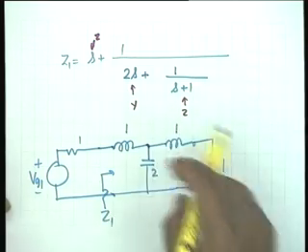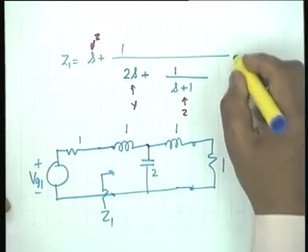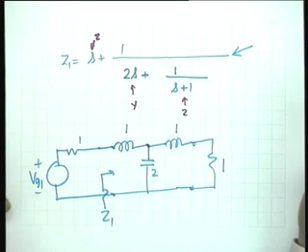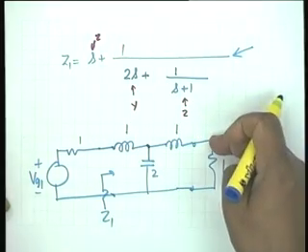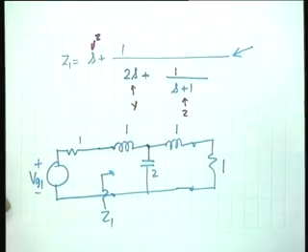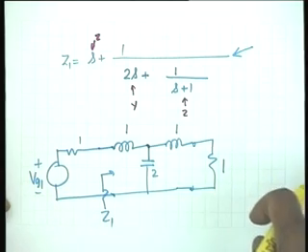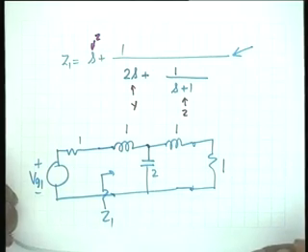Okay. The mechanization of this, as is obvious from this expression, is to expand the given function in continued fraction. This is a continued fraction, a plus 1 by b plus 1 by c plus and so on and so forth. So the mechanization is that of continued fraction, and we shall do this again with continued fraction rather than arguing from removal of poles. Removal of poles was done to explain to you the actual mechanism of network synthesis. We were removing poles one by one, poles at infinity.